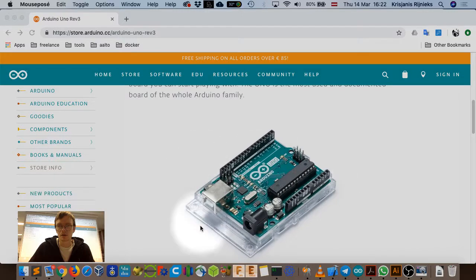Yeah, this is the clock over here. Then they added also a USB port, which allows your computer to communicate with it. Then there's an ISP port, which is used to burn the bootloader. Arduinos usually come with a bootloader already on the chip, which makes it possible to program it by using the USB interface. And then it has these little sockets over here, which are basically mapping directly to the pins on the ATmega microcontroller chip over here.